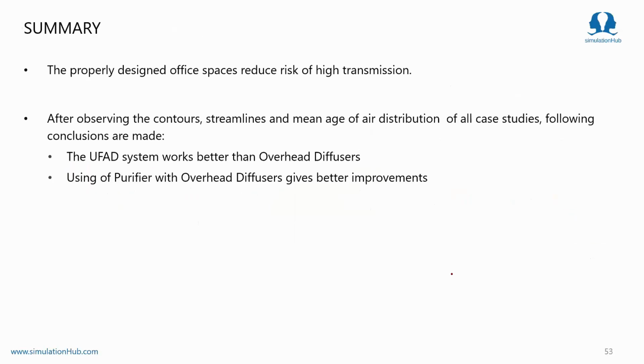So now let's summarize our case study. After observing all our contours, streamlines, and mean age of air distribution, we can say that the overhead diffuser is less effective compared to the UFAD system in terms of performance. So overall the UFAD system is a good design.